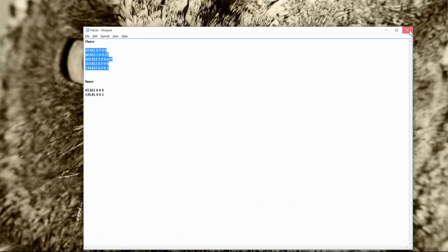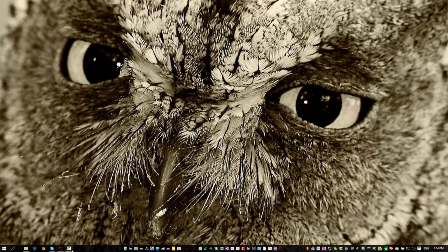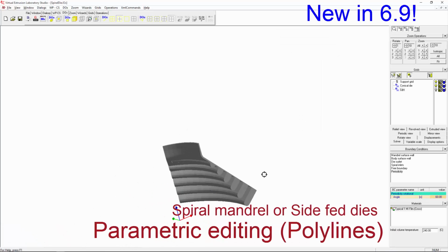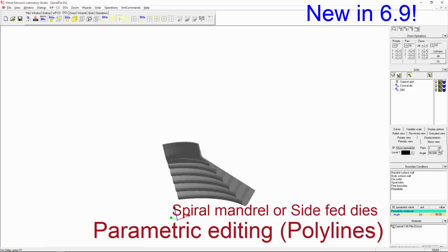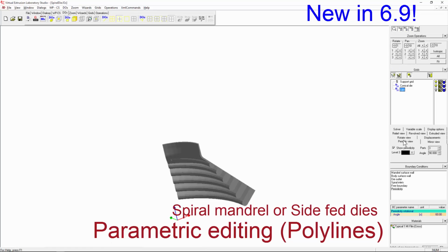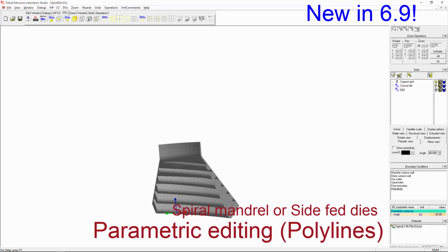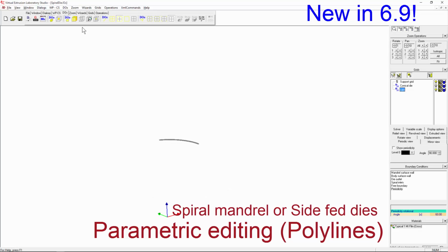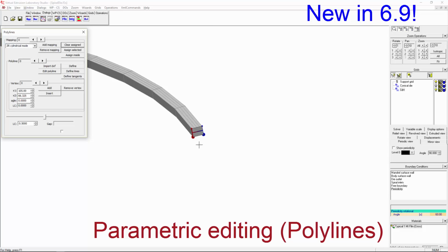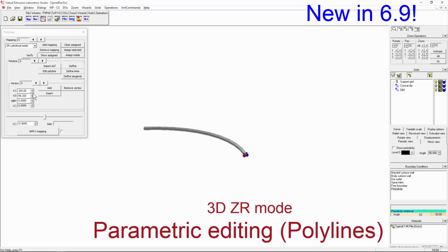Another possibility for using parametric design is for spiral mandrel dies. This is a conical die with periodicity. It's really periodic geometry. I've built a small ellipse on the top. And very easily, similarly as before, I can use two simple lines and assign whatever is inside. Now I can simply stretch and deform them any way I like. So let me make this taller and smaller in diameter.